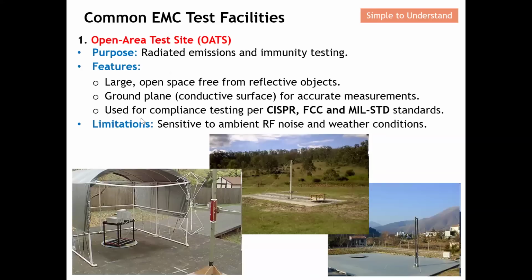So this open area test site is mainly used for compliance tests per CISPR standard, FCC, and also the MIL standard. The limitation of this open area test site is very severe, especially nowadays in Singapore. You can hardly find any place that doesn't have cellular service. So when you use this open area test site, it is very vulnerable and sensitive to ambient RF noise and also weather conditions. So basically this is getting more and more challenging now.